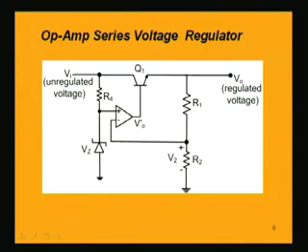The other point, which is connected across R2, will be dependent upon the output voltage, because what is V2? If we look into the voltage across this R2, this is V0 into, again voltage division like the earlier case, V0 into R2 by R1 plus R2, this is the voltage V2.